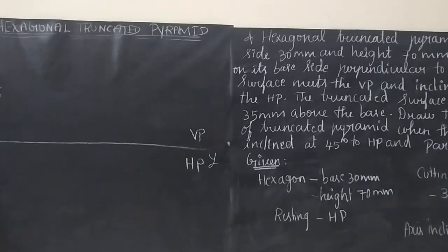So what we will be doing, just see here, we will be taking this point, right? Try to move it horizontally to the nearest slant edge, either left side or right side, anything we can do. I'm just moving to the left hand side. Keep your scale here and move this point horizontally to the nearest slant edge, that is O dash B dash. After that, try to draw an imaginary line vertically downwards like this. You can also use your scale, and draw the line very, very lightly.